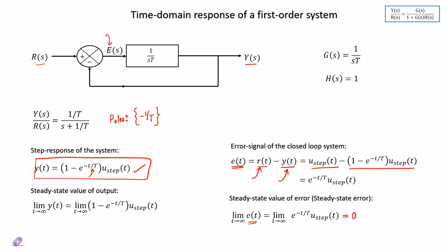Okay. So what we will do now is see a simulation where we say that the transfer function Y(s) by R(s) is equal to p by s plus p. So basically p is equal to 1 by T. I will vary p and see what the effect of varying p is. Suppose the example that I have taken, maybe you can take something else also, if I start with 2 by s plus 2, then where is the pole of the system?